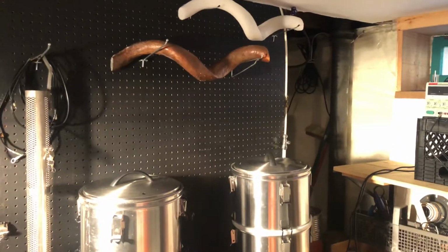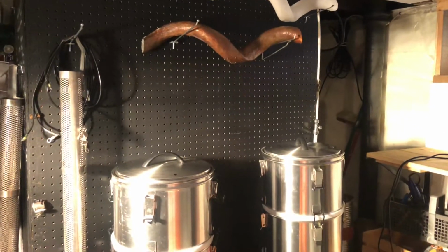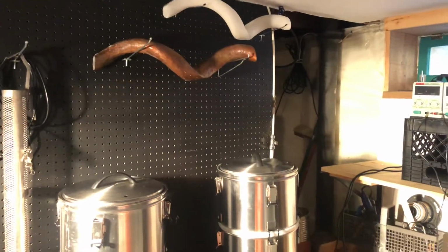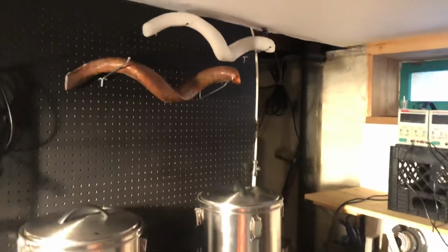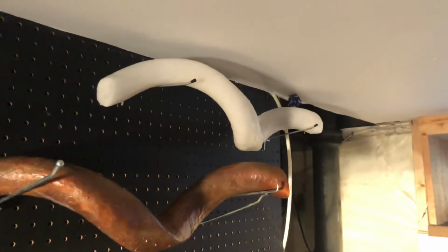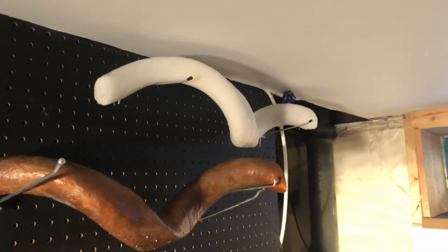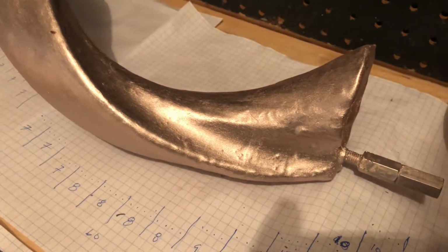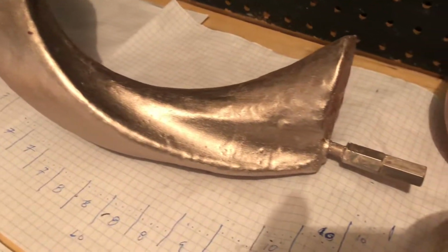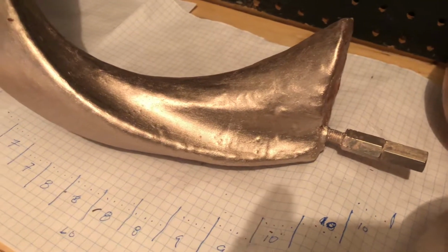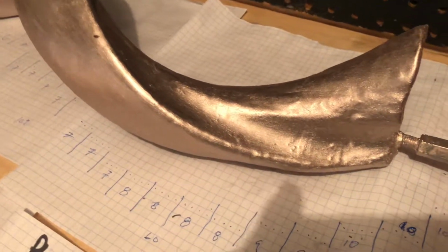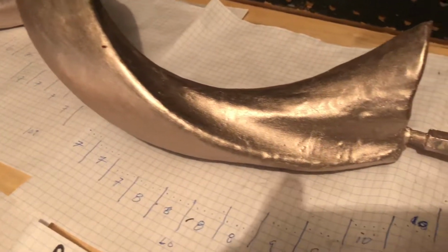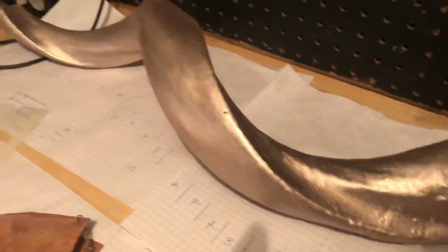But in simple terms, what I do is fill the horn up with wax, let it cool, dip it in boiling water, and extract the form. And then I modify that form to what you see here on the table. To get the spiral groove, I half carve and half melt it out, starting at the top and melting it out such that the wax flows through the groove and does not alter the surface texture of the rest of the part.